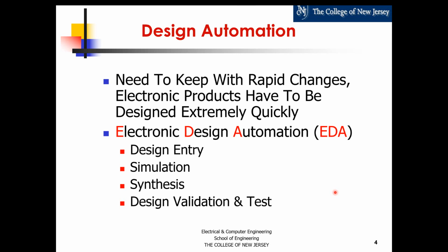So Verilog is part of design automation. It's just one part of what you're going to be doing: the entry of the design into this paradigm of electronic design automation, because of complexity. The big part where the productivity comes in is here in the synthesis part. What that means is that you are not hooking up transistors, or an abstraction of circuitry made by transistors, which are logic gates.